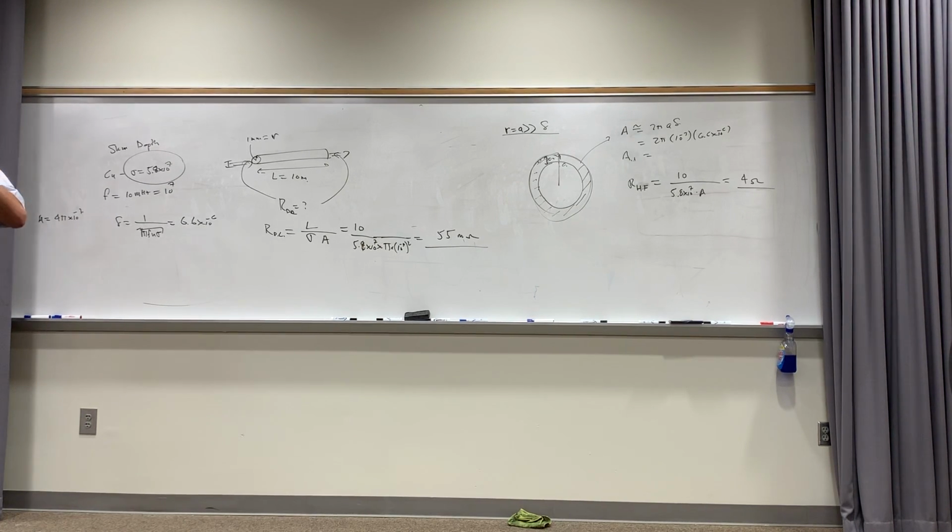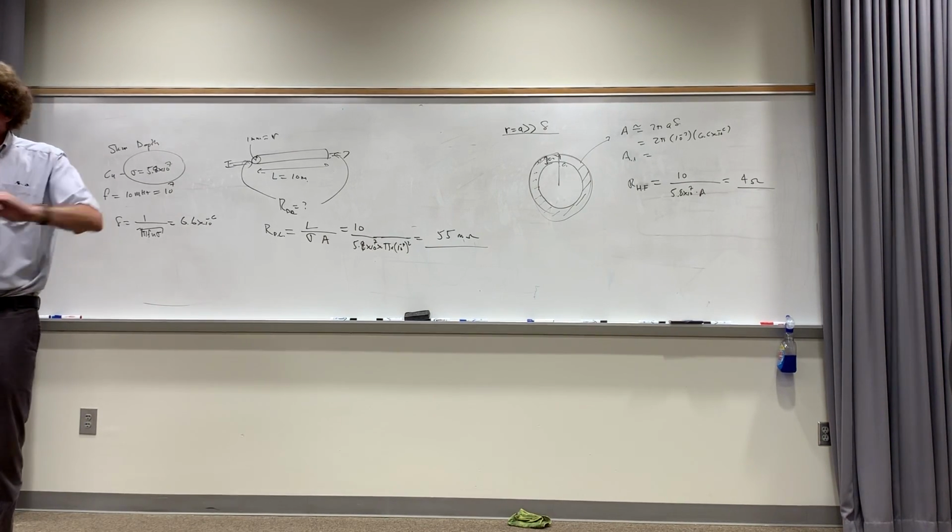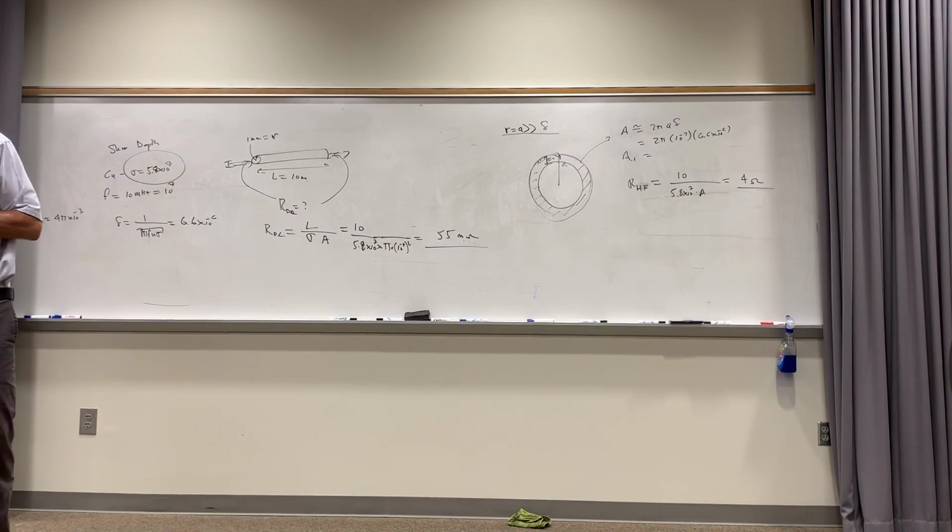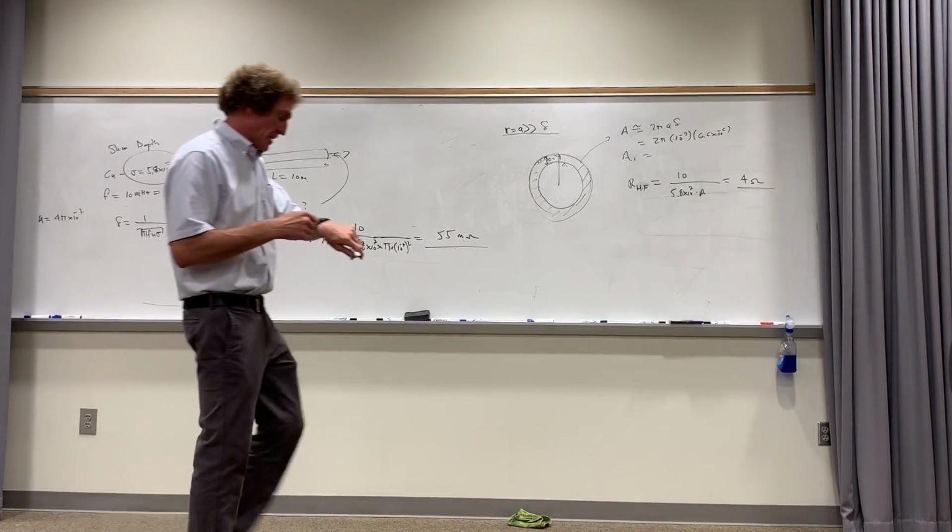In other words, all it is is a shell, hollow on the inside, because all that current's flowing on the outside anyway. Usually what they choose to do is use a whole lot of thin fibers of wire coated with plastic or an insulator and bundle them. And that's twisted pair bundling. It's so they can get more of the signal down the line without the attenuation, just the actual ohmic attenuation.